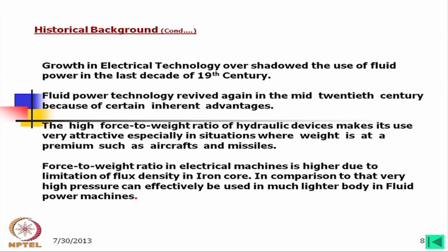In comparison to that, very high pressure can effectively be used in a much lighter body in fluid power machines, because fluid power ultimately generates stress in the body as the pressure is distributed all over the cavity. So, the body in which the fluid is being pressurized is also stressed in a distributed manner, and the stress level can be kept within the limit for very high pressure.